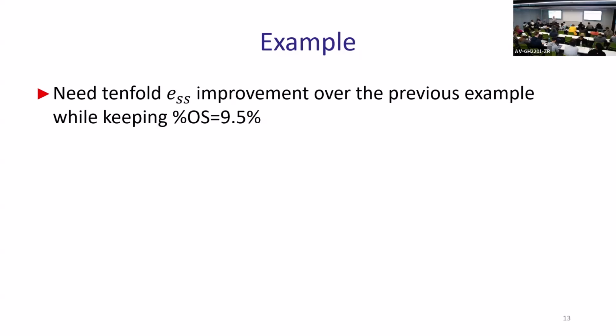Why is that? Because ESS is equal to K times, because this is just the DC gain, so it's G of 0, okay? When you multiply that by S, because KV, if you remember, is the limit of S times G, you cancel the zero at 0 and the pole at 0, and you're taking the rest of the G function at 0.